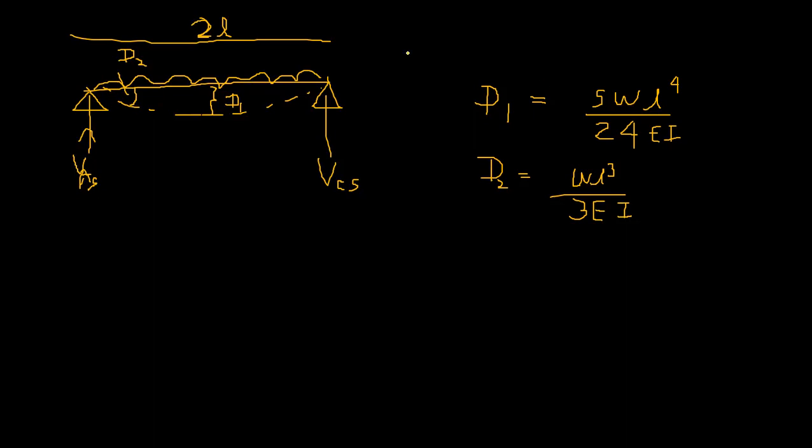So how to determine the sign now? So it is actually in the downward direction, right? So that means this is negative according to your sign convention. Why? You took upward deflection and upward forces as positive. Here you took clockwise rotation and clockwise moments as positive, and this D2 is actually in the clockwise direction, right?